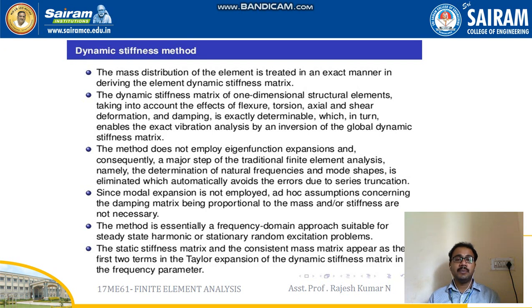The method does not employ eigenfunction expansion and consequently a major step of the traditional finite element analysis, namely the determination of natural frequencies and mode shapes, is eliminated, which automatically avoids the errors due to series truncation.